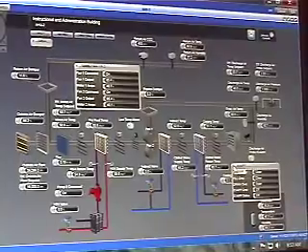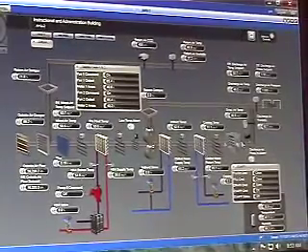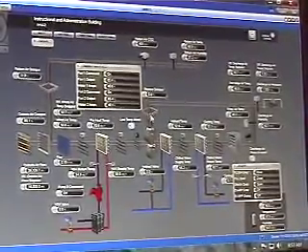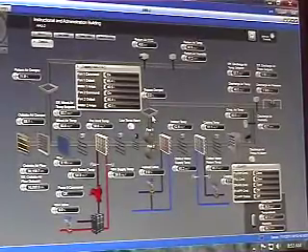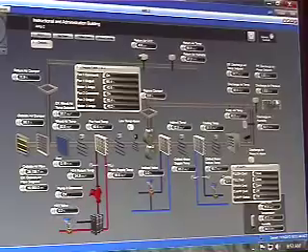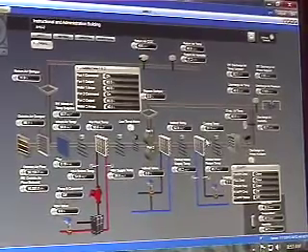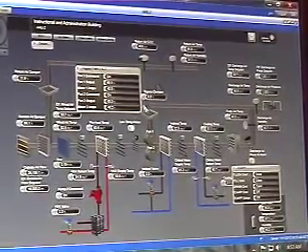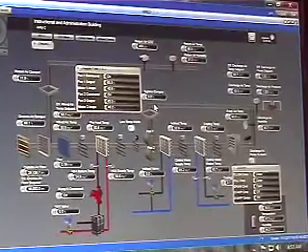We then modulate to maintain temperature using this. If it gets too cold, we open and close this damper right here to allow air to either go through the evap media or go up and around to bypass that evap media. So this is where the control of this damper comes into effect. So you shouldn't get those really big temperature swings, like 60 degrees, evap media on, it drops 20 degrees. It should be very gradual and smooth. You should have a lot of controllability doing it this way.